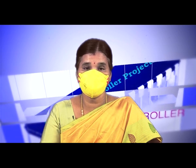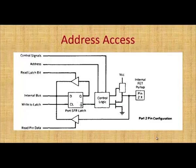In the port 2, now we will discuss how the address will be accessed. For accessing the address, already we have discussed, this is I1, this is the I naught signal, right. So, address is connected to the I1 signal. So, now I am giving the control signal as 1. So, you consider this is a mux, 2 signals I naught and I1, one output, right. Either it will be connected with the I naught or it will be connected with the I1. So, which of I naught or I1 is selected is based on this selection line. This is a 2 cross 1 mux. So, based on that concept here they have selected the control logic.